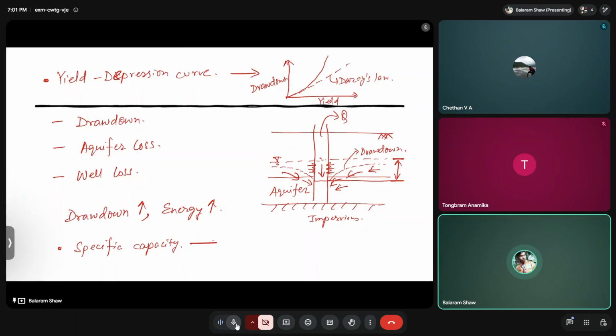It will give you how much water you can extract from aquifers or wells. Generally there is something called yield factor. A designer will consider this yield factor to design at what optimum rate the pumping should happen. This yield factor is given as the ratio of specific capacity to the aquifer thickness which is screened.